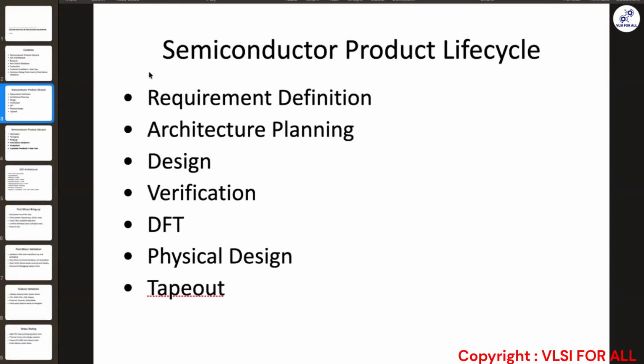Then it goes to the DFT, design for test. In this phase, you insert logic because in the post silicon phase, you may have to debug certain things of your IP or your SoC. You may have to read the registers for it.